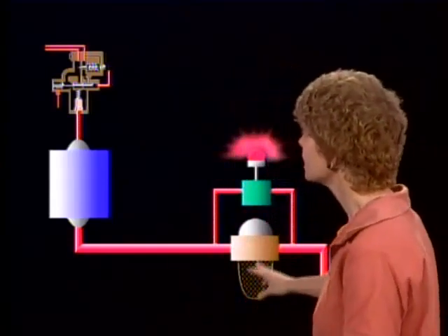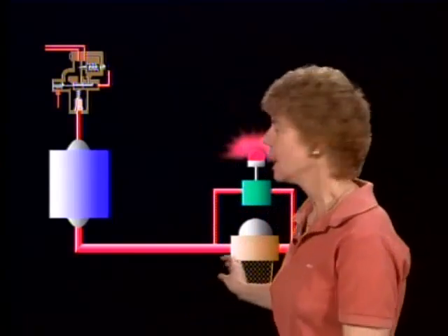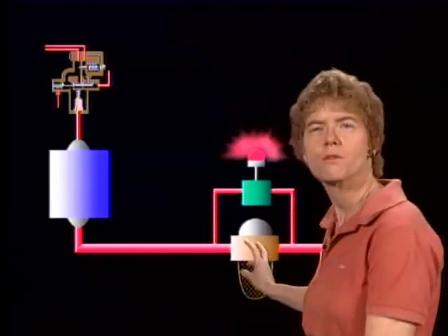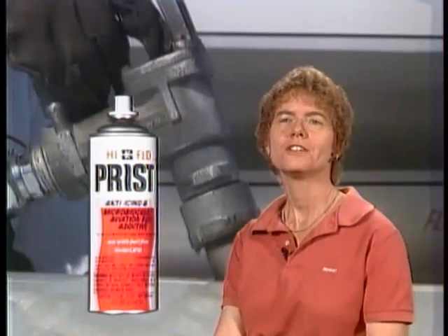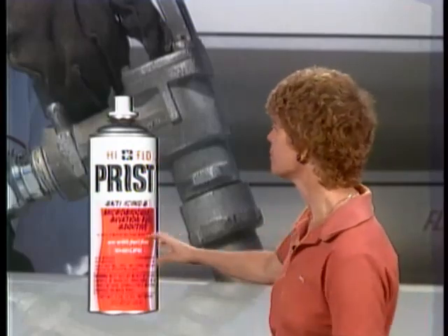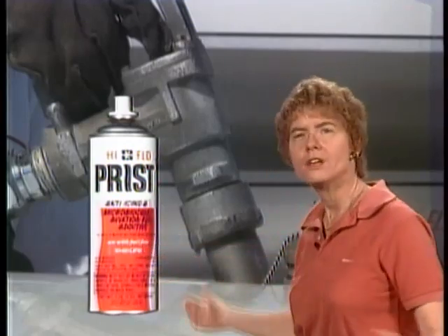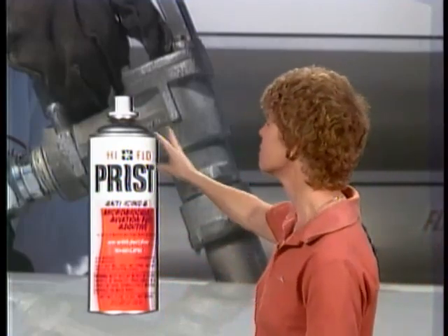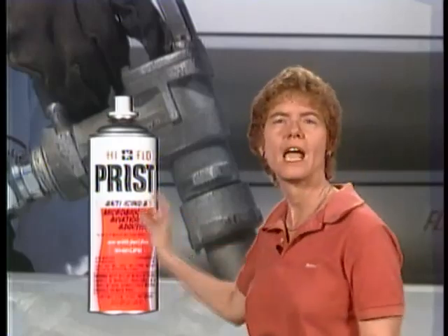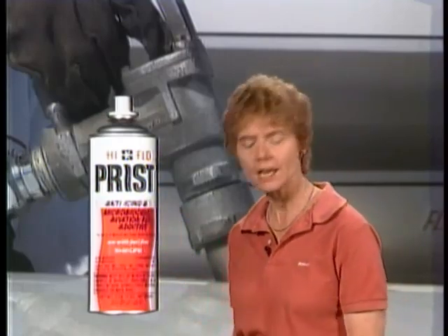turbine engines are very susceptible to forming ice in the fuel filters. And you want to prevent the ice from forming in the fuel filters, and a very common way of doing that is to add anti-icing fuel additives. You can heat the fuel, which we'll talk about in a minute, but another way to take care of the problem is to add anti-icing fuel additives.